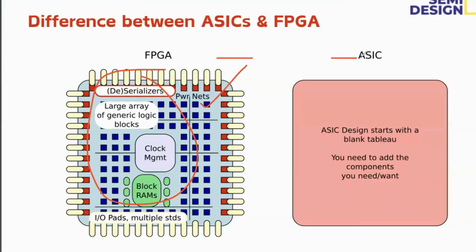Most of the companies, whatever they are manufacturing the chip, introducing some processor, they won't directly do the manufacturing with the ASIC chip. First, they will confirm with the FPGA chip only, because FPGAs are reprogrammable, right? If any mistake, error or debugging things are there, we can easily do that. But if you do directly with an ASIC chip, if any circuit mismatch or wrong connections are there, the whole chip will be spoiled, right? That's why they will check with the FPGA. That is the difference between FPGA and the ASIC.